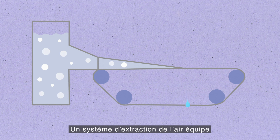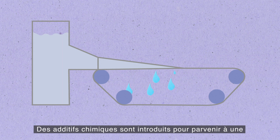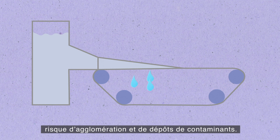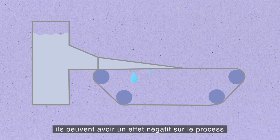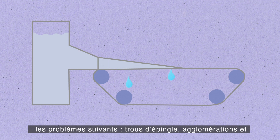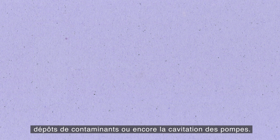Talking about drainage, entrained air in the stock reduces dewatering capacity on wire section. The paper-making process is equipped with an air removal system. To ensure optimum deaeration, deaerator chemicals are used. Proper deaeration helps to prevent deposits in the system. If overdosed, they can be harmful to the process. If deaeration is poor, this can lead to problems such as pinholes, deposits, and pump cavitation.